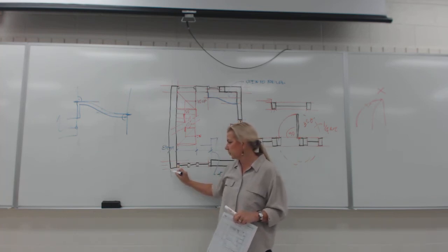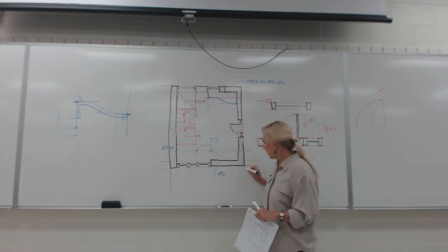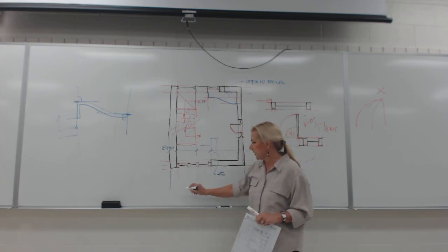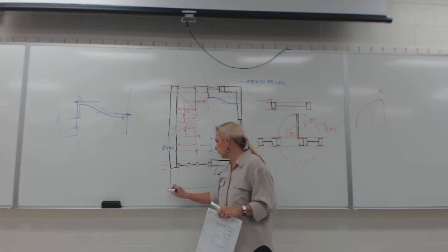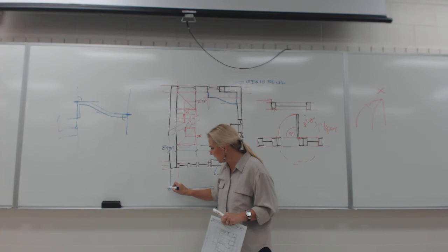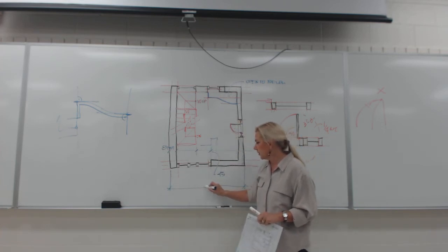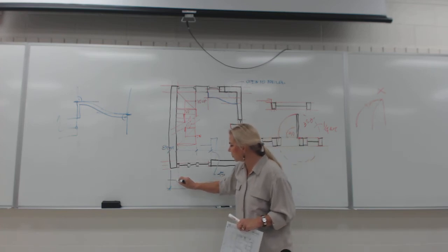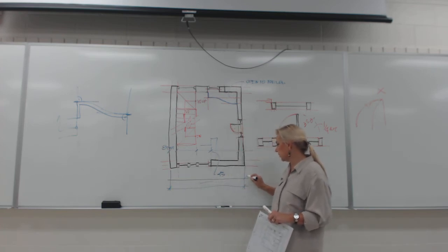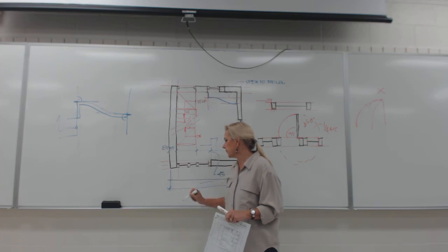You leave a small gap. You draw what we call extension lines, and on the top or bottom, you have to give us the overall dimension, and these lines extend slightly too. So you're going to say 20 feet here, 0 inches. But there needs to be another string, about 10 millimeters apart, about a quarter inch.